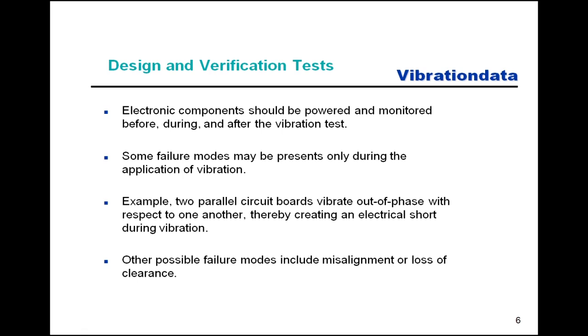Well, at that point you can save a lot of time just by stopping the test and then going and doing your failure investigation. If you wait too long, something else might happen or whatever. So it's good just to be aware right away if the component is failing during vibration test.